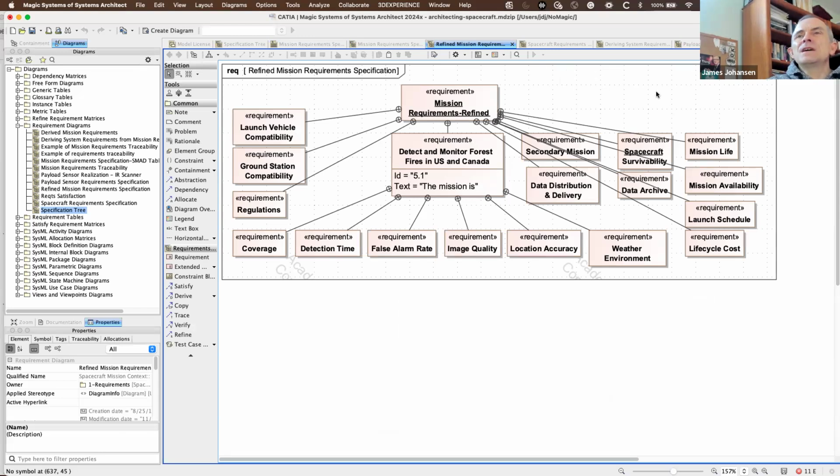Then we get into the next level of requirements. Here we need to think about what kind of launch vehicle I am going to be using. If anyone has ever looked at the James Webb Space Telescope, you might have noticed that the collecting mirror folds up. They did that because it needed to be small enough to fit into the fairing, the top of the launch vehicle where they contain the satellite, because there wasn't a launch vehicle that could handle it fully deployed.